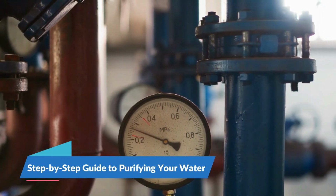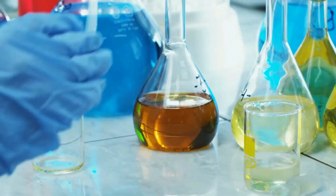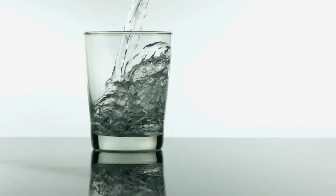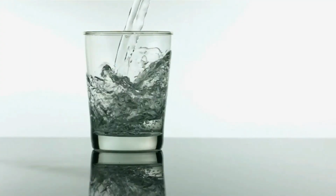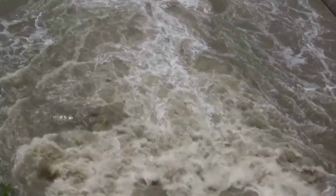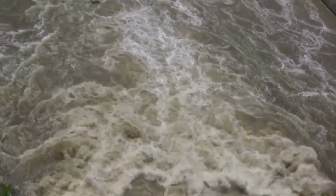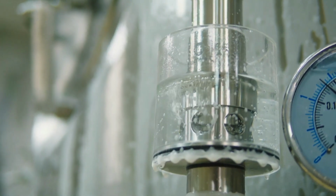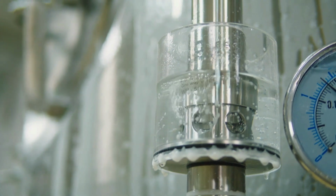Step-by-step guide to purifying your water. Number 1. Preparation. Measuring chemicals. Learn how to accurately measure the amount of chemical needed based on your water volume. This might involve calculating dosages or using pre-measured tablets. Pre-treatment. If your water has visible particulate matter or is discolored, pre-filter the water too. Remove solids before adding chemicals to achieve better results.